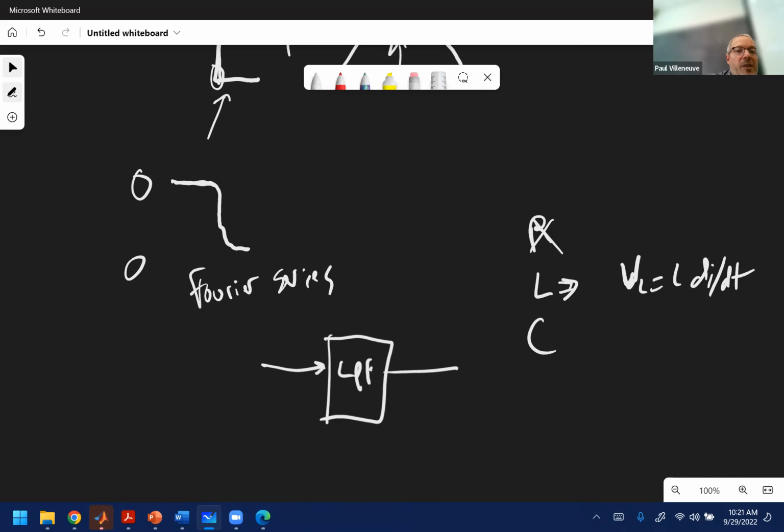So what we would have is something that looks like this. It's 0, spikes up crazy high, and then goes back to 0. So if we put an inductor there, does our output voltage, which is a sawtooth, look like this? Not even close, right? So probably can't be an inductor. Let's look at a capacitor.